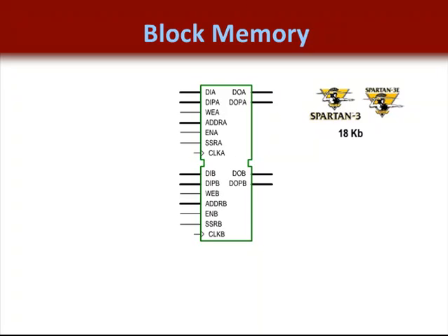The embedded blocks of RAM provided in the Spartan-3 devices each provide 18 kilobits of RAM or ROM storage. These blocks also have a reasonable degree of flexibility that you can exploit to lower costs. The block RAMs are fully synchronous. Data is written on a clock edge when the write enable is active. Data is read from a given address and transferred to the output on a clock edge. The port enable must be high for any operation to take place.